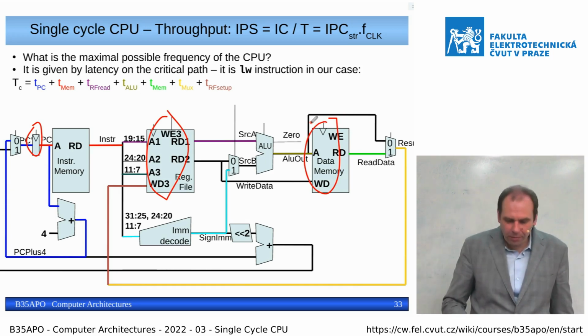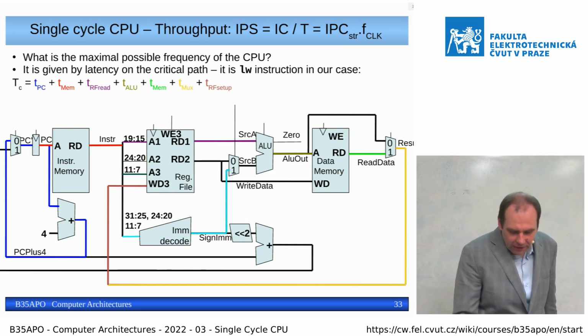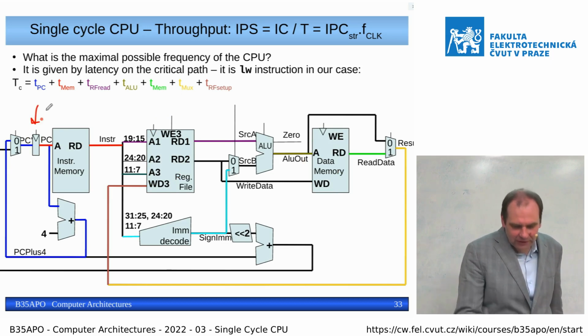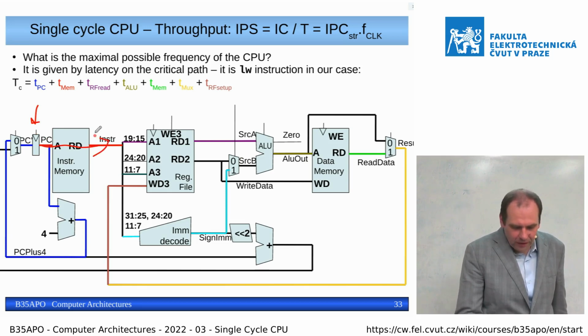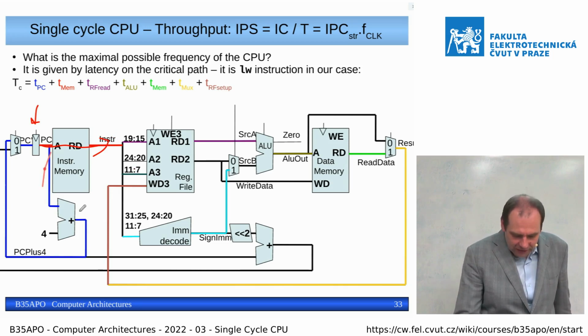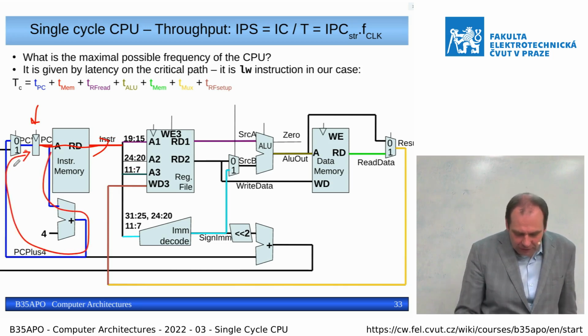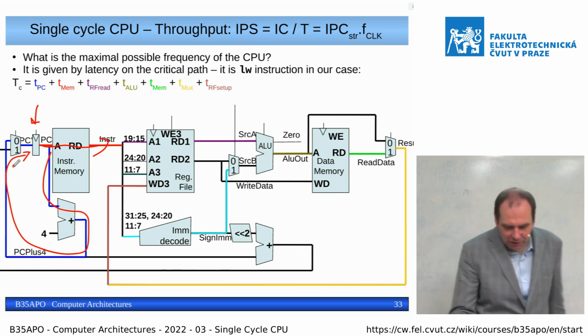We have there a problem with the speed, because at the moment when we select the instruction, and store the next program counter, we need to wait for the time to fetch the instruction. In fact, the addition is running in parallel, but it is fast, so we do not need to consider this path.